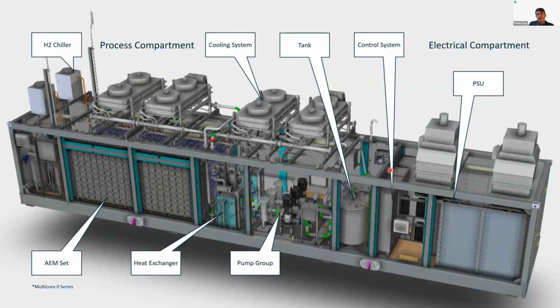This is a welded wall in between, and there's no gas coming through. Then we work with an overpressure on the electrical compartment. So we have permanent overpressure here, so it's not possible for hydrogen to go through a hole in this wall. We have no holes in this wall, and basically the material is steel here. Okay, thanks for that.